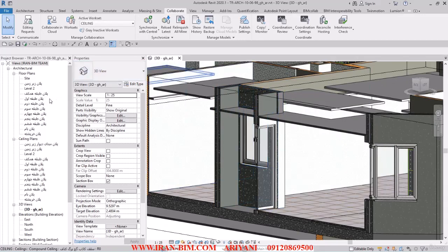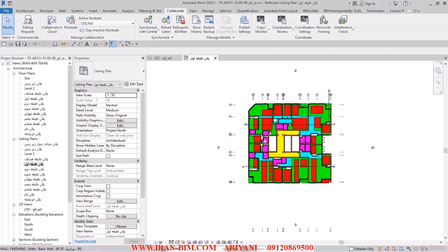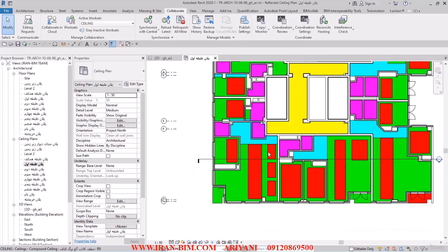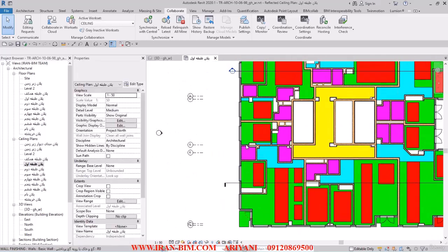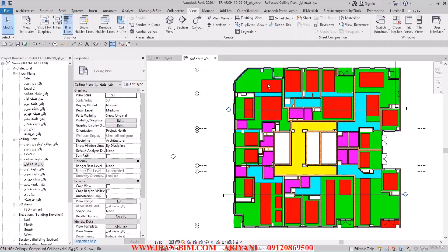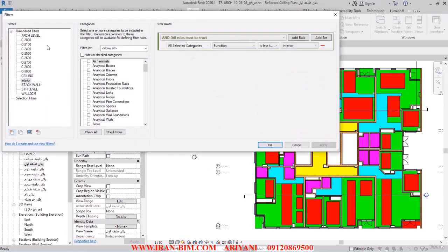The next important point is when we're drawing the suspended ceiling for the first floor here. Because we have different dimensions and heights, it's hard to figure out which one needs to go where, because we did have different types of it in the CAD file. To do this more easily, we can use the filter here. As you can see, I've chosen color as a filter.